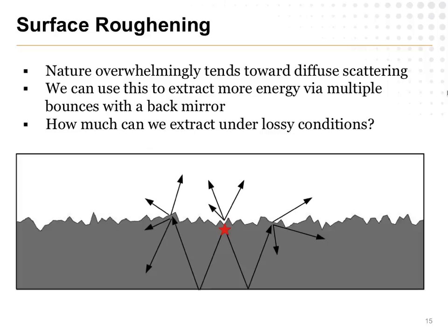And we're going to do the same thing, only now instead of calculating how much power is absorbed inside of this thing, I want to know how much power is getting out. It's really the same math, you're just solving for different terms. All I have to remember is that technically this is a lossy material. There might be some p-n junction where all the action is occurring, but there's going to be some bulk material that's going to reabsorb photons and convert them to heat.